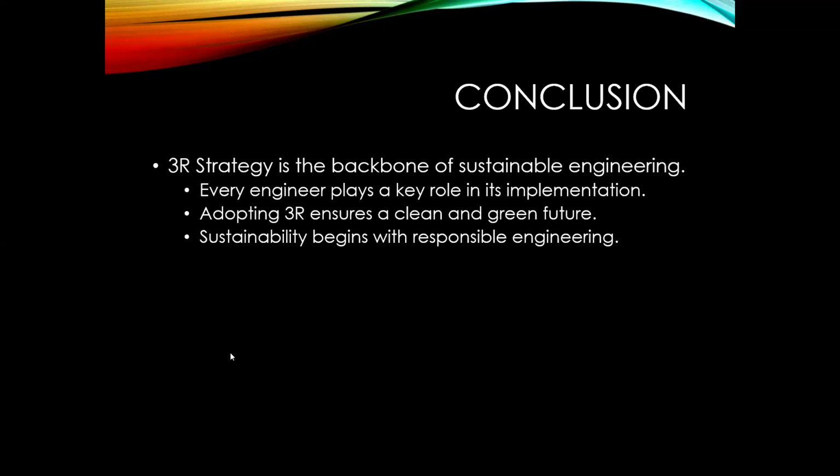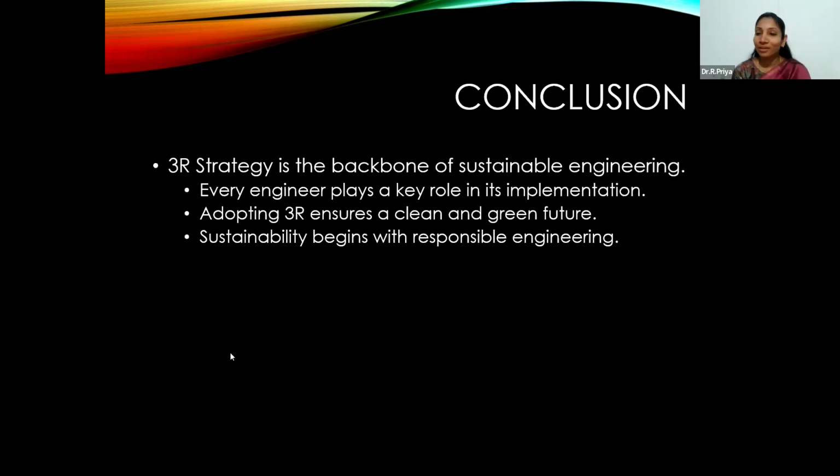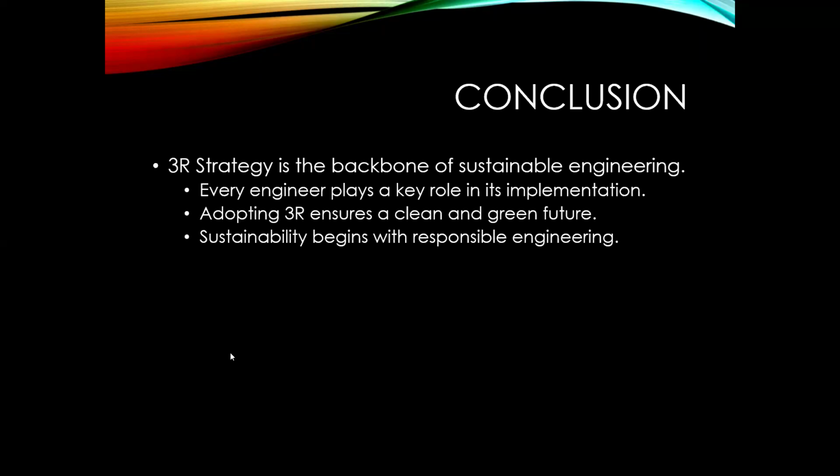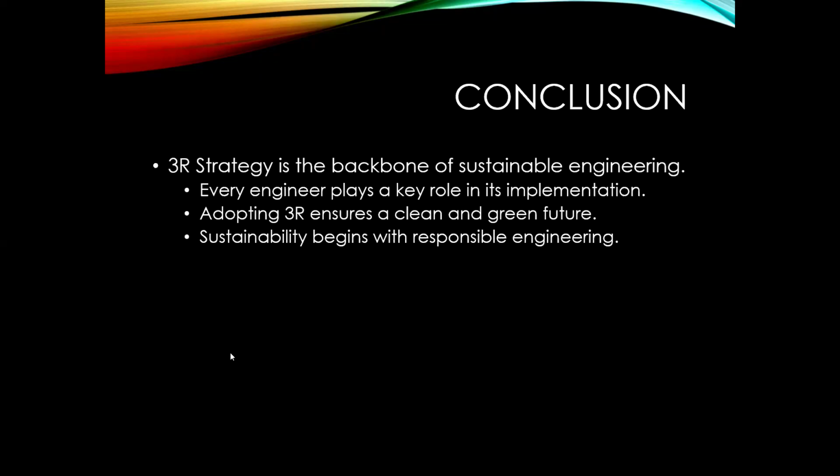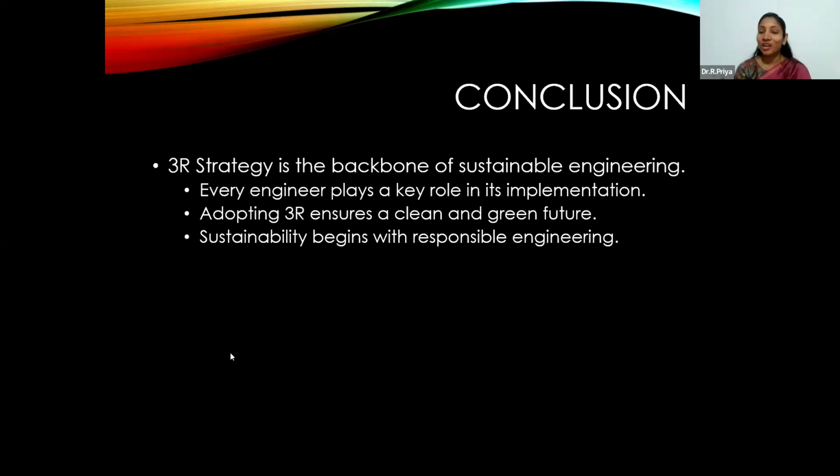Yes, ma'am. In one of the projects we are doing here, we are using recycled aggregate material for the road base. Wherever we collect the milling material from the asphalt, we reuse it as aggregate road base, as a sustainability measure. We are using it on around 60 kilometers of roads. Oh, good, good, John.